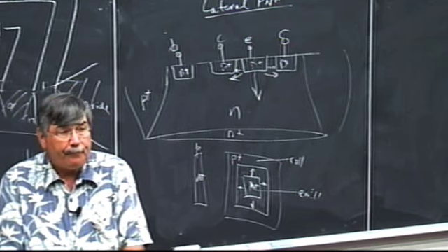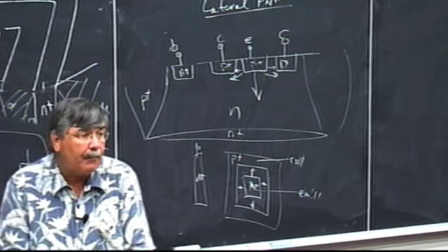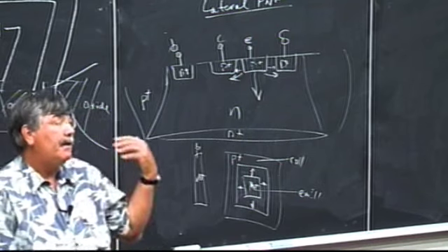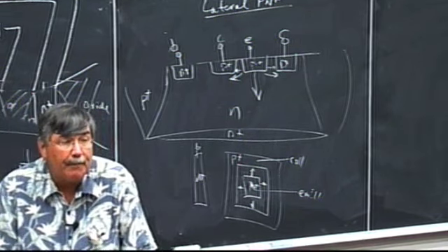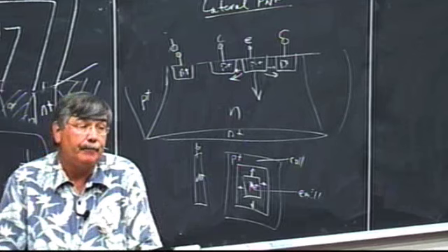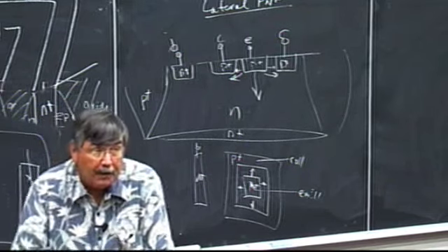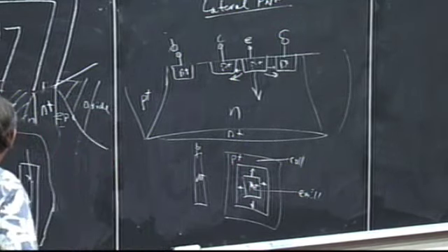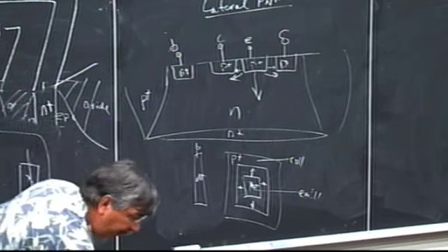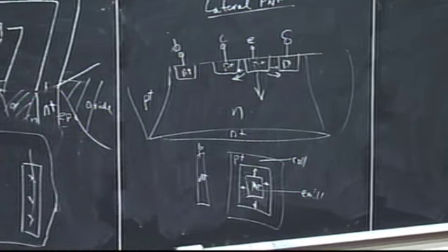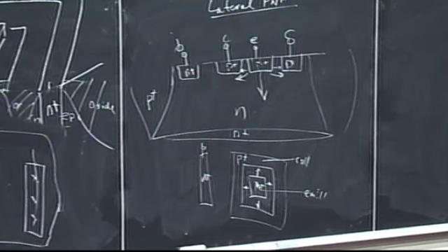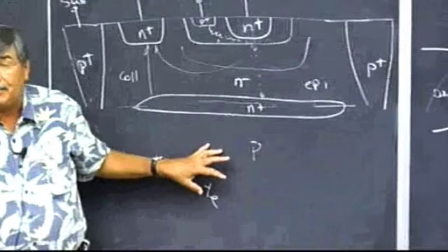Yes? Why did we start with a P-type substrate? Again, we're optimizing for a good quality vertical NPN, and we wanted them isolated. So in all these processes, I erased this. Let's go over to the board here. So I need the isolation. In order to be able to build multiple transistors in the same substrate, I need to have them electrically disconnected.